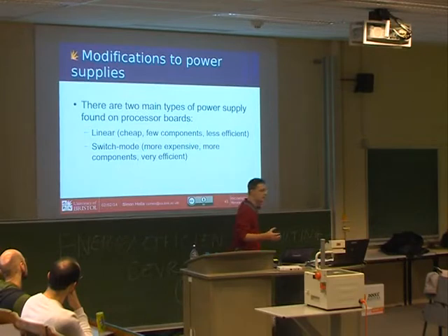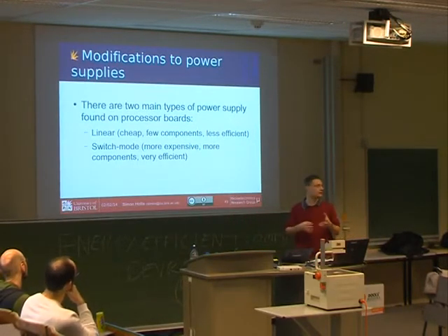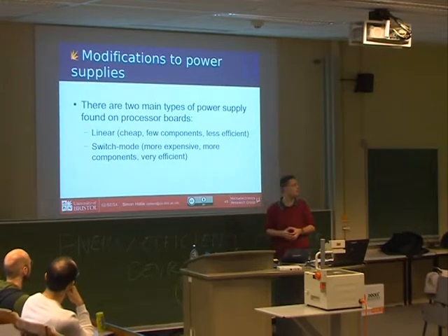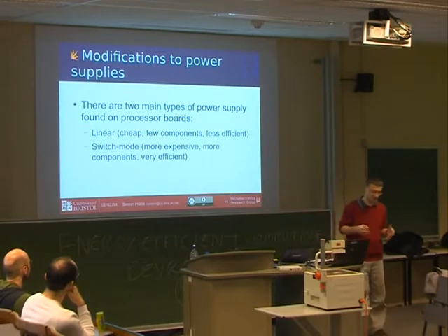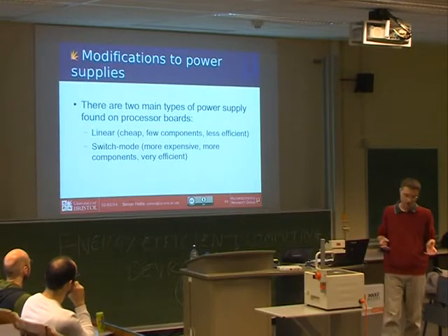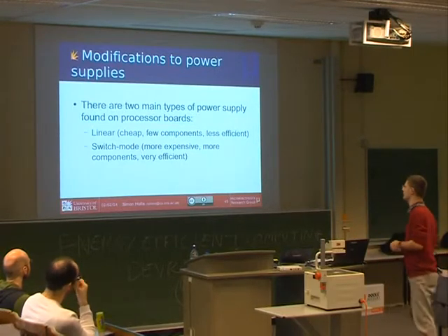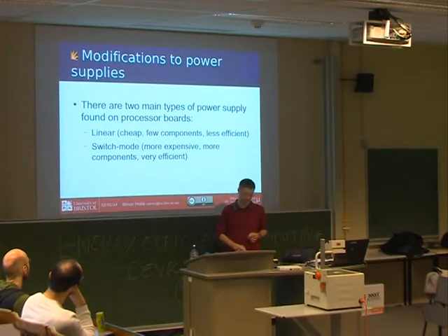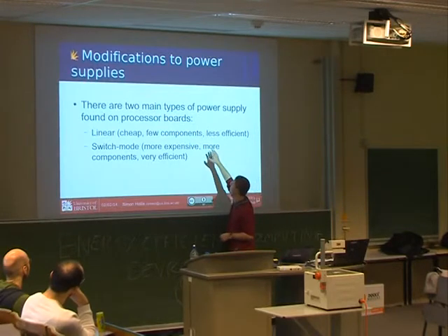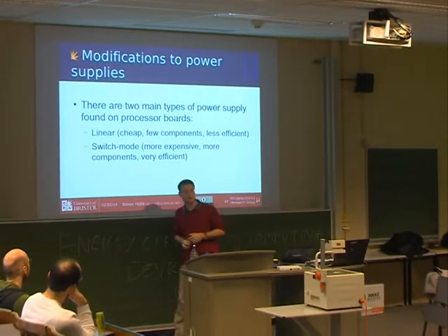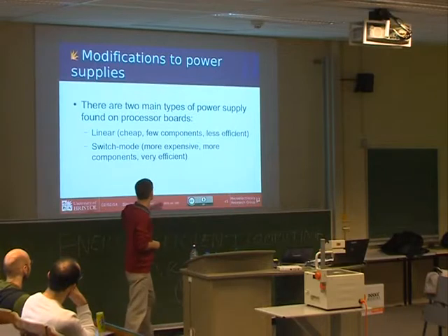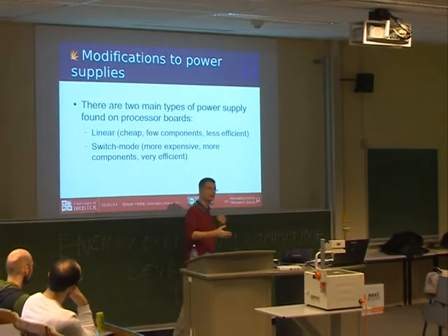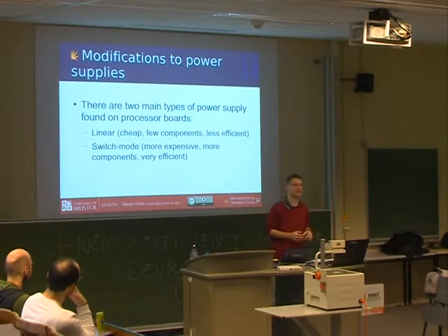And there's two popular types of power supply, and they have different components. On small, cheap devices, you typically find this thing called a linear power supply. It's good because it's very cheap and very small, but it's pretty inefficient, so it's not used for large devices that get too hot. And those devices use switch mode power supplies. That's the kind of power supply you've got for a laptop. It's much more efficient. These things here, depending on what you put in, might be as bad as 20%, 30% efficient. These ones here are normally 98+% efficient.